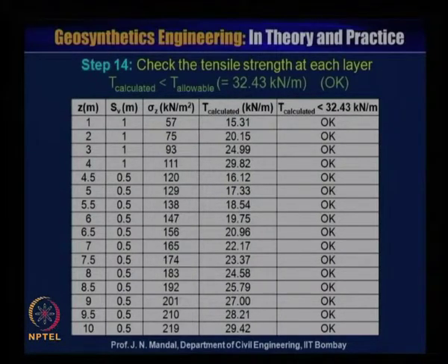In this table, you can see this is the 10 meter height of the wall, and up to this depth of 4.5 meter we are keeping the spacing between the two reinforcements at 0.5 meter, and for the remaining we are keeping 1 meter spacing.